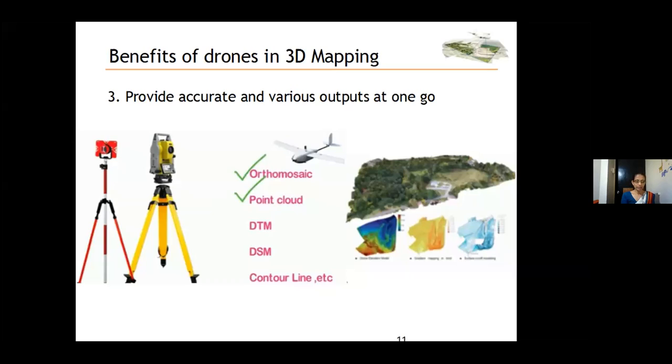So how accurate is a drone survey then? The performance and type of drone, the quality of its components, the camera resolution, the height at which the drone flies, the vegetation, and the method used to geolocate the area images can heavily influence the accuracy of drone survey mapping. At this point, it is possible to reach an absolute accuracy down to 1 centimeter and also 0.7 centimeter ground sample distance under optimal conditions with a high-end surveying drone. Okay.